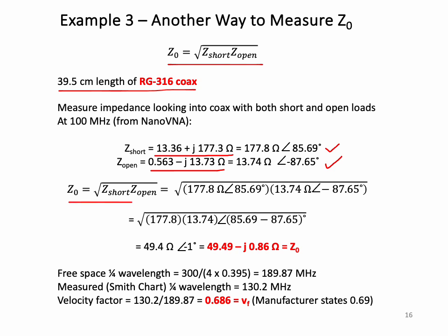So I take Z0 being equal to the square root of the product of those two numbers, and if I use magnitude and phase, it's much easier to compute the square root. These two equations come down to finally here, which gives me an impedance of 49.5 ohms roughly, with a small capacitive reactive component of 0.86 ohms.